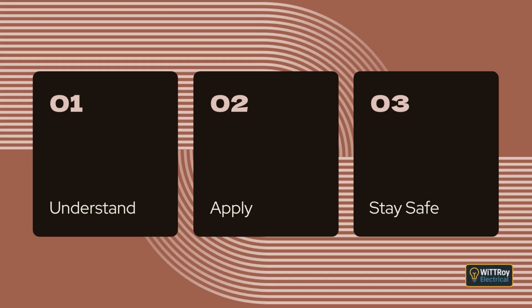Clause 2.9.2.3, Location of main switchboard. The main switchboard needs to be easy for people to reach. It must be placed where someone can quickly get to it from an entrance to the building. This is because the main switchboard is the central point for controlling the installation.